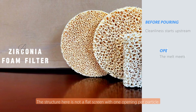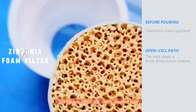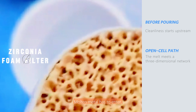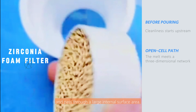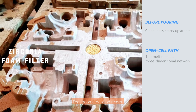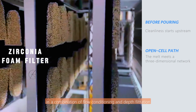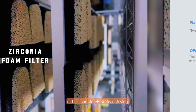The structure here is not a flat screen with one opening per particle. It is a three-dimensional interconnected foam. Molten metal has to enter, divide, turn, reconnect, and pass through a large internal surface area. That geometry is the reason ceramic foam filtration behaves as a combination of flow conditioning and depth filtration rather than simple surface sieving.